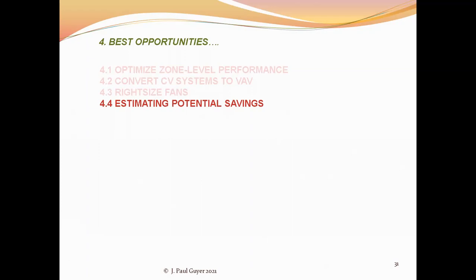However, building maintenance staff is typically limited to just one method of determining the potential for right sizing, measuring fan system static pressure. Measure the main supply fan system static pressure on a hot, humid day. Make sure that all fan vanes and dampers are fully open. If the measured static pressure is greater than the design pressure, the fan is probably supplying too much air and is a good candidate for right sizing.